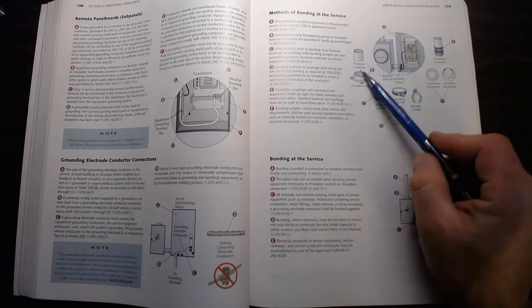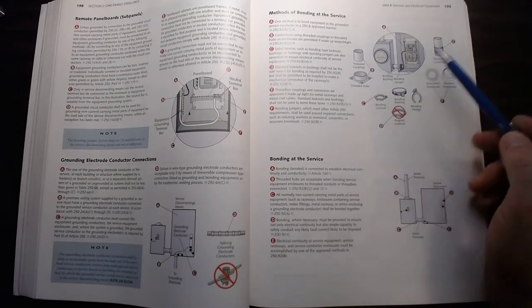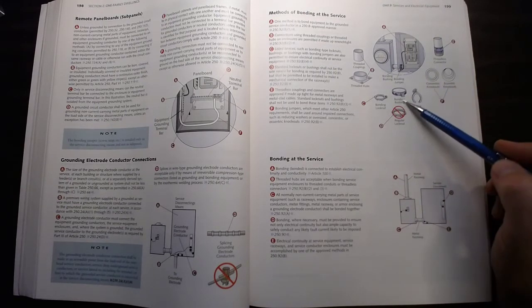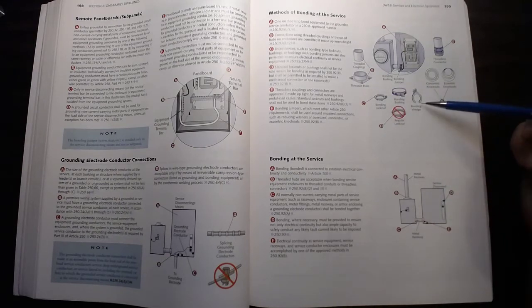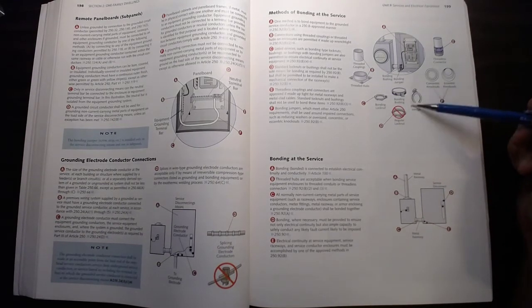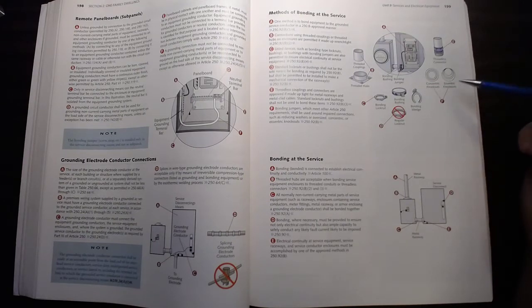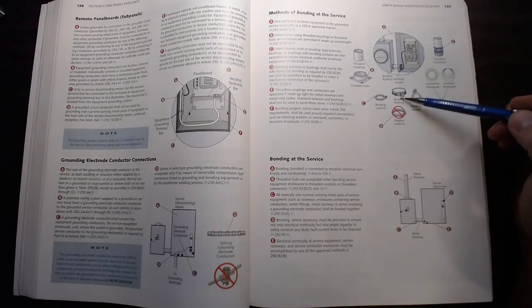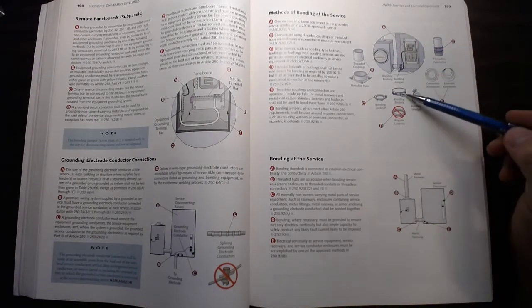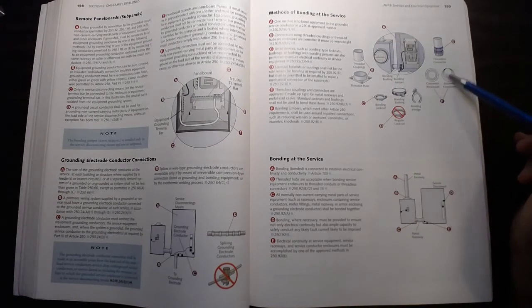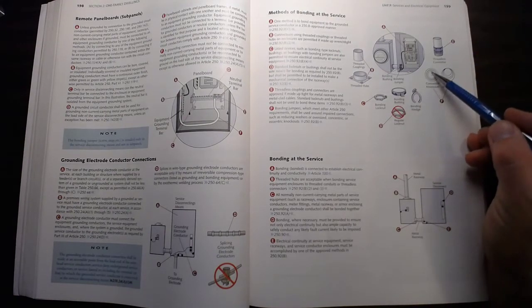Methods of bonding at the service can be threaded hubs. We would need to put in ground bushings here. So these types of ground bushings are available. This wedge bushing is a good option if you've already pulled the wire and landed it and you need to put it in. You can work this around the conductor and you can land it onto the termination. Whenever you have concentric knockouts or eccentric knockouts, you need to put in ground bushings to make sure that the raceway is properly bonded and grounded. These concentric and eccentric type of fittings, they can move and they can break open, and they just have a couple tabs holding them in place, so they're not good ground connections.